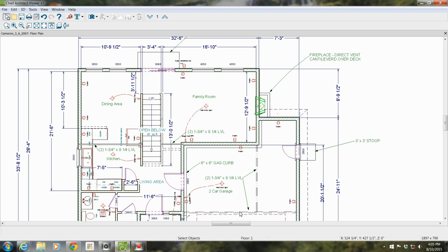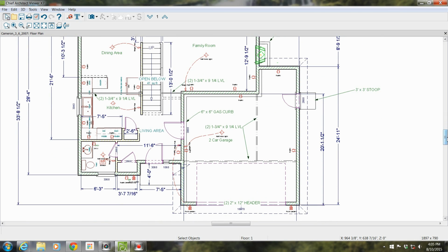The floor for the garage comes up flat, and then the curb is raised up 6 inches. 6 inches out, 6 inches up, so that if gas leaked out of your car or any kind of hazardous fluid in the garage, oil, whatever, it would get to that curb and it would stay and pool in the garage and not go into the living area. So that's required. It would go from wherever the foundation would intercept the interior of the house.